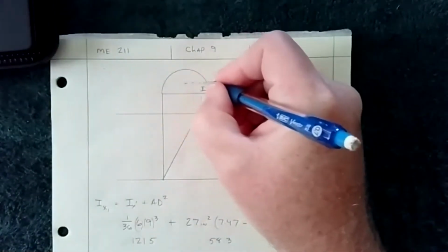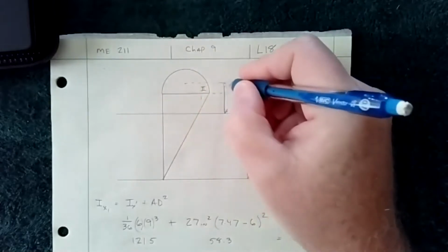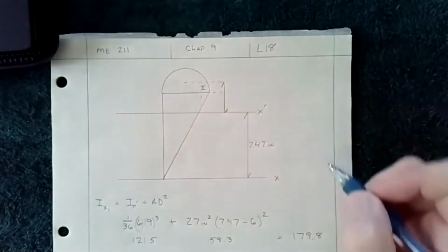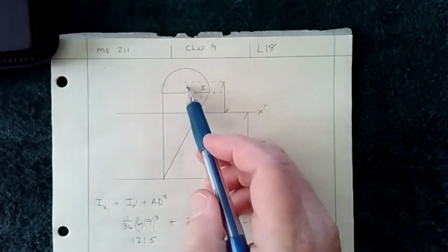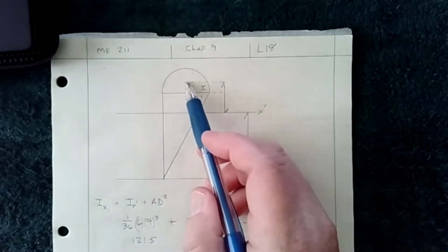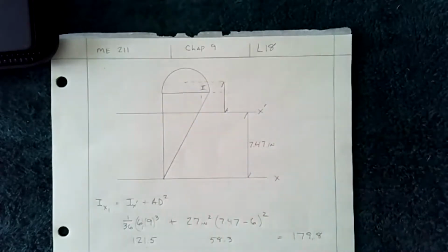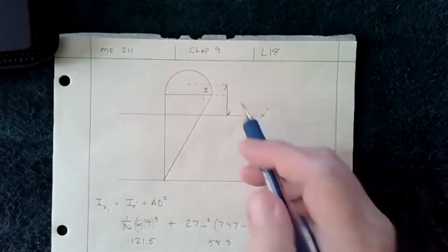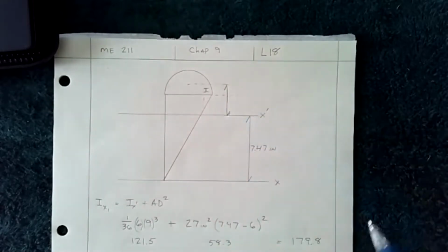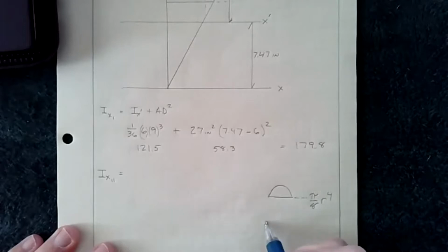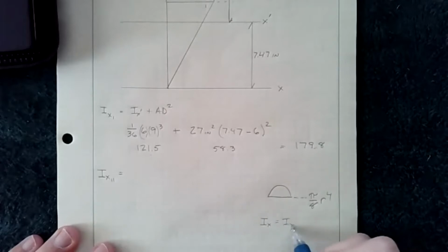Now we know the centroid location because we know that that height there is 4 over 3 pi, and we found it in the previous problem. But the question then is, what is the equation about the centroid? So what is the moment of inertia? What is Ix prime about it? So actually, it's not a hard thing to derive because to derive it, you can use this relationship here, and you can say, well, I know that Ix equals Ix prime plus AD squared.